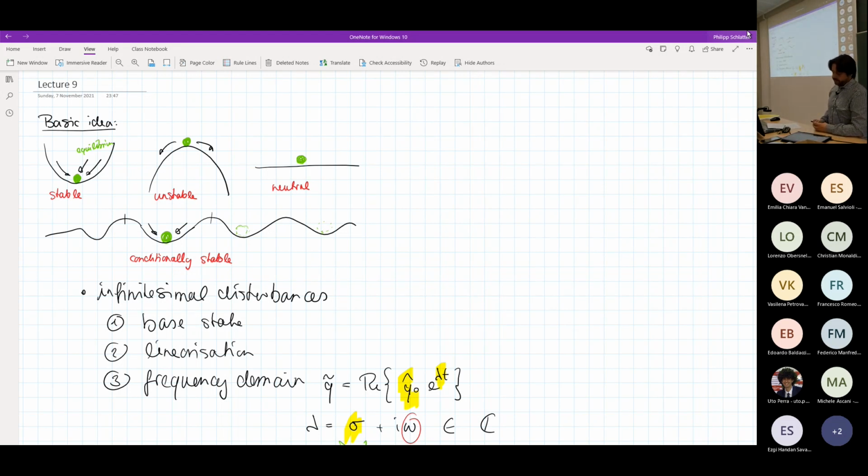Okay, so today we're going to talk more about stability, in particular the stability of viscous shear flows. Essentially we will end up with what is called the Orr-Sommerfeld equations, and we will apply them to channel flow. I have some MATLAB demonstration where you can see how we can use these equations to get real solutions in channel flow. But before we do that, which will be the main part of today, as usual, I would like to summarize very briefly what we have done so far.